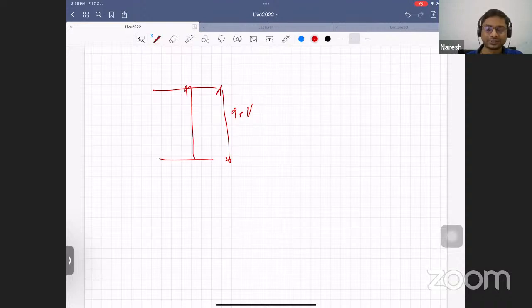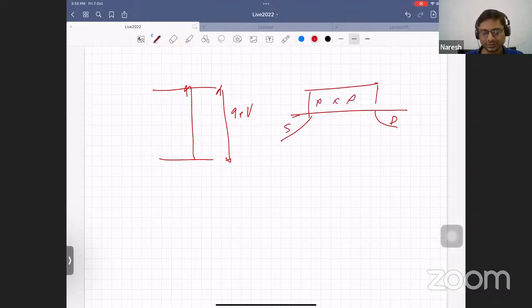So when you have a transistor, you have this nice source, drain, and so on. But if you send it into space, the X-rays will cause some defects to come here, and that will cause threshold voltage shifts. So there was a lot of study done in the late 70s and early 80s to make what are known as radiation hard devices.